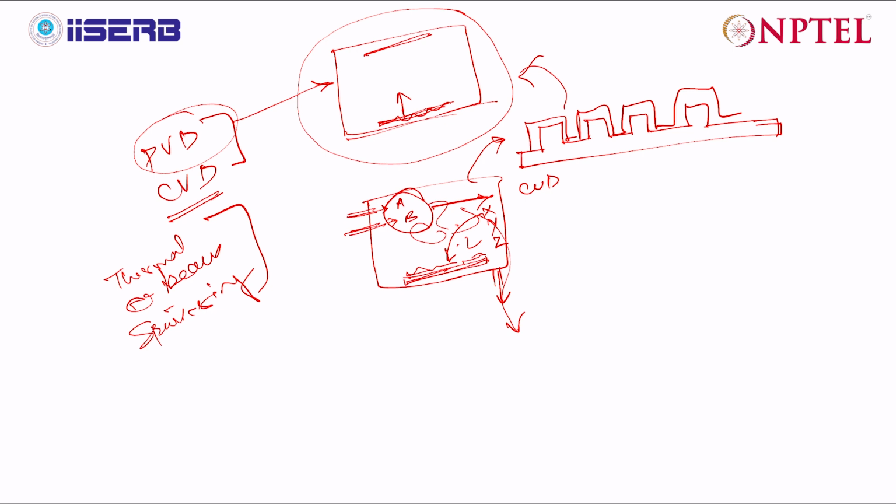So before you decide upon the fabrication associated with the sensor that you are making, it's better that you first decide which technique you are going to implement, and then you can decide the process flow. So everything is associated with the process flow. You may find that CVD is a better option in case of a certain sensor. Although you have an option of PVD, you can also go ahead with PVD, but CVD is giving you better film thickness, film uniformity, and quality of the film.